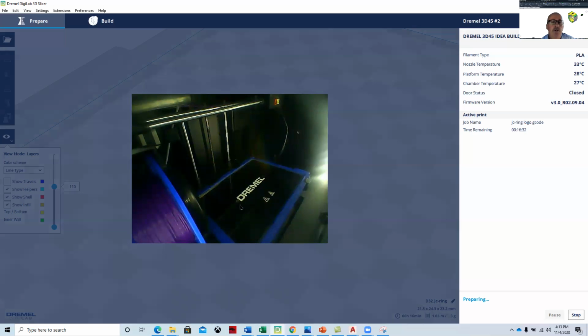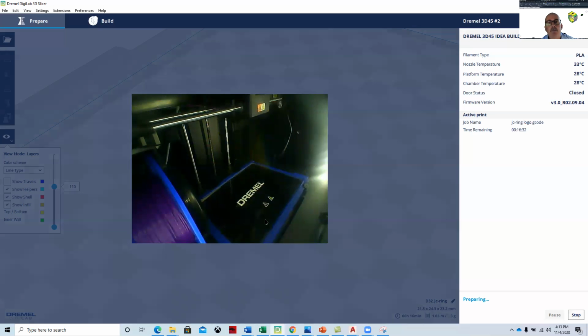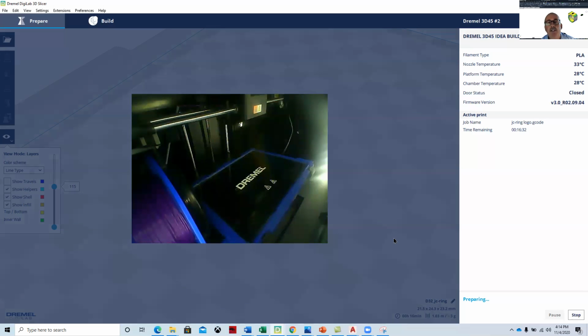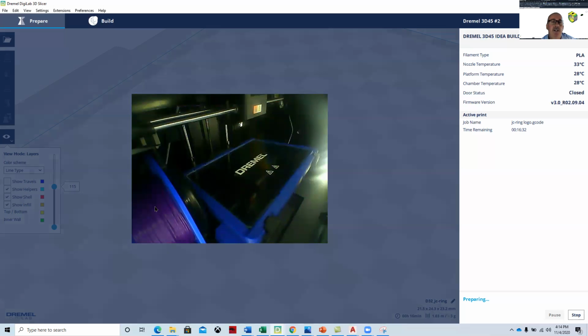So the first thing the printer will do is calibrate the flatness of the pallet. It's going to start up here, and then touch off on the top of the pallet just to make sure that it's level. Usually I'll go through and change the filament. I probably should have, because the filament has a tendency to dry out and crack.